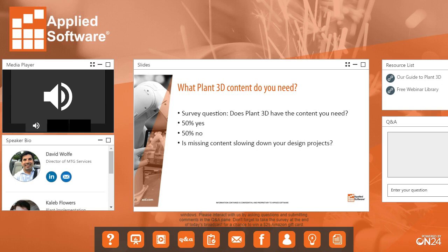So have you used the long description styles at all? That's the closest thing I can think of right now, long description styles inside of Plant 3D, where you could set up some style definitions, and as long as you build your catalogs correctly, then you can populate and build specs on the fly with the correct component descriptions. So that's probably something we need to review a little more in depth in a future webinar, because there are some challenges with it. A lot of times people want to see, let's say on a reducer that changes schedule, the main by reducing schedule.